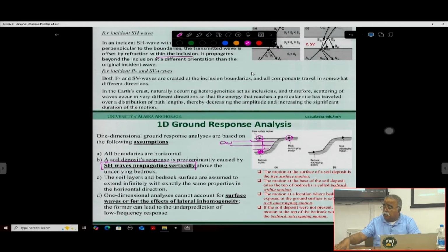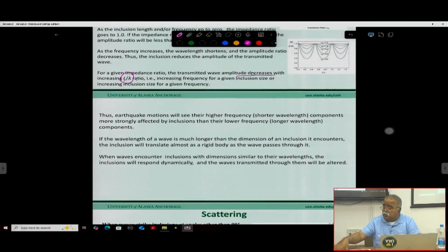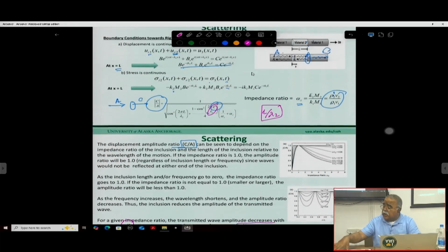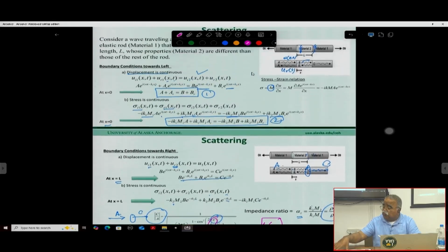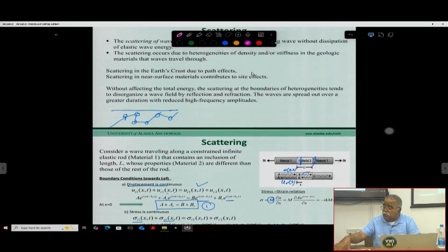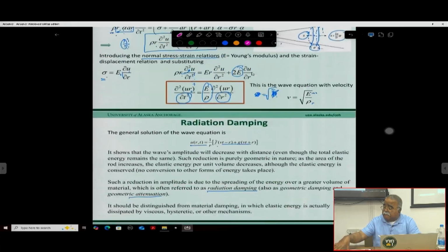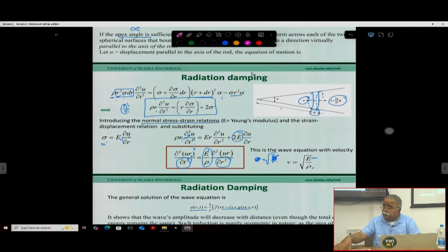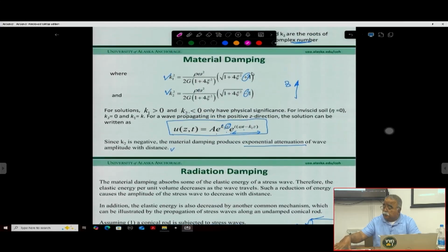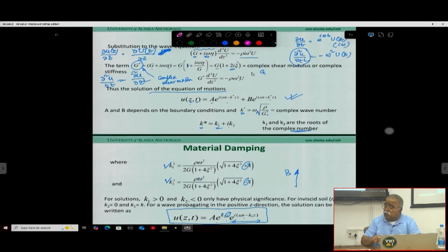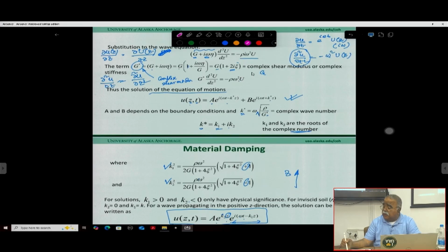Here I have put the different moduli and the different things in terms of all your k values or the damping values. Here I had shown you all the different k star equals G star by this, and then put that G star equals G into 1 plus 2i damping. So put this number here and take it on the upside.